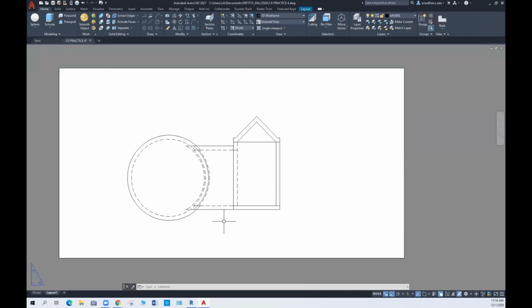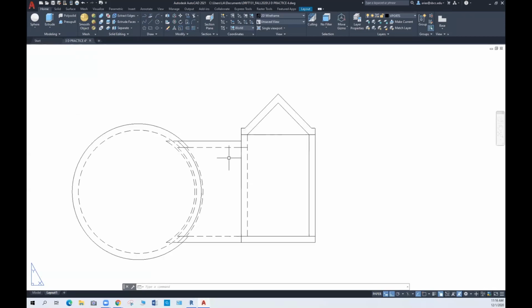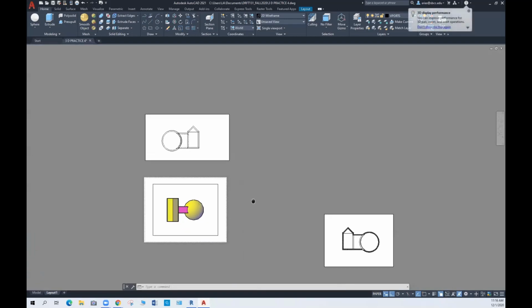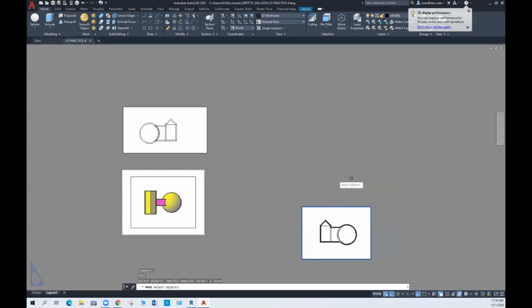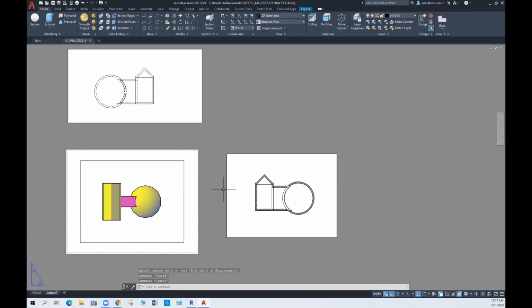And that's what the program can do. Again, you can create a section anywhere in the solid, and then the program will draw the 2D lines that create the outline of the object. And that's the whole idea. Meaning that when you create a 3D model, you can use these tools to create the 2D views of that model without having to actually redraw 2D lines to do it.